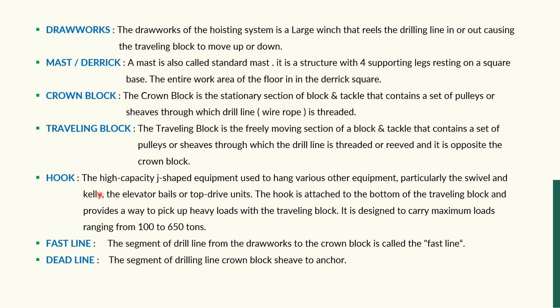Hook. The high-capacity J-shaped equipment used to hang various other equipment, particularly the swivel and the Kelly. If it is a Kelly drive rig, then the Kelly will hang in the hook. Suppose it is a top drive rig, TDS rig, then in that case, the TDS will hang under the hook, the elevator belts or the top drive units. The hook is attached to the bottom of the traveling block.